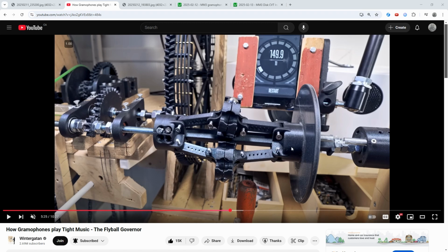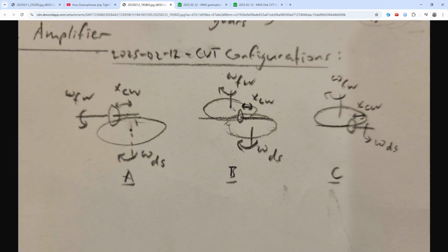That is, to operate it as a tachometer. Then imagine using the position of this sleeve to set the position of a control wheel, over here, to set the gear ratio between these upper and lower CVT discs. That connection implies that if the drive shaft speed decreases by a certain percentage, then this control wheel will move such that the gear ratio will decrease towards 0.